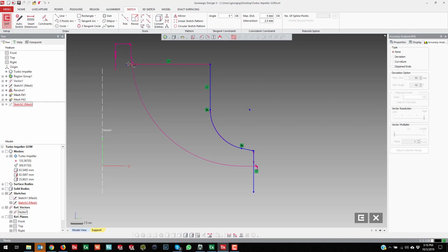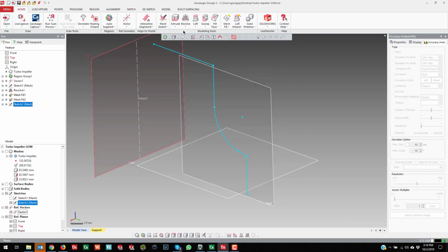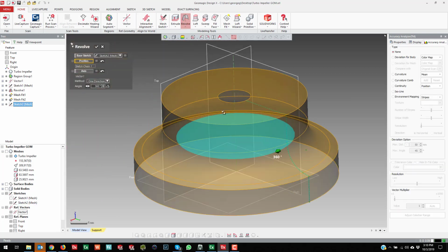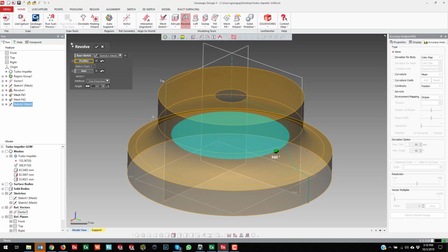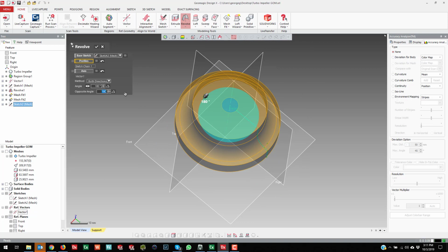And I make sure that I extend this past the inside because I'm going to use this as a surface trim later on. You'll see what I mean. And when I do my revolve, make sure I revolve it as a surface. Now, because of the way I'm going to be trimming stuff together, I don't want my revolve surface to go all the way around because it makes the trimming more difficult in the software. So if I go to both directions and then I drag these arrows backwards, so I'll go ahead and type in 10. There we go.